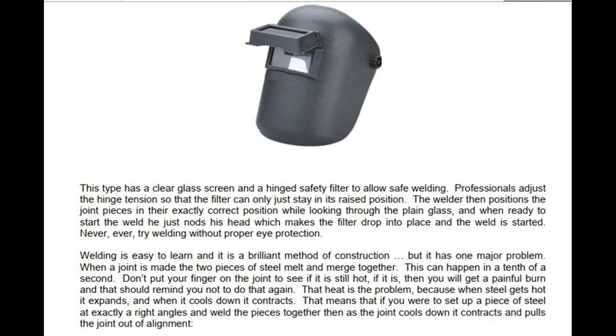The welder then positions the joint pieces in their exactly correct position while looking through the plain glass, and when ready to start the weld he just nods his head, which makes the filter drop into place and the weld is started. Never, ever, try welding without proper eye protection.